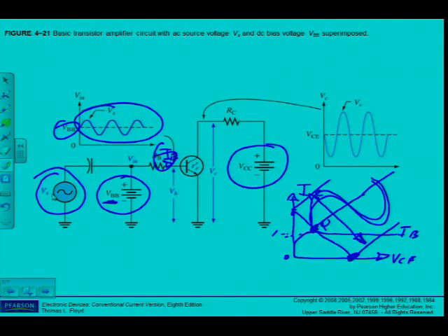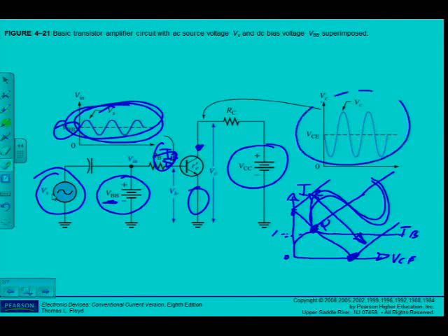And then the output will be taken at the collector for my amplifier. You can see here at VCE, it's actually VC, but VCE and VC is the same thing because there's no resistor at the emitter as mentioned earlier. And I can see, and we will discuss this later on, that from my input signal, my output signal is amplified, although it's 180 degrees out of phase, which we will also discuss in later lessons. So that is the transistor being used basically as an amplifier.